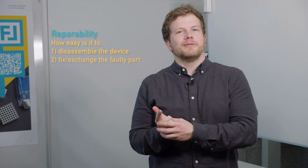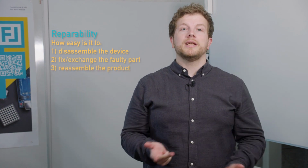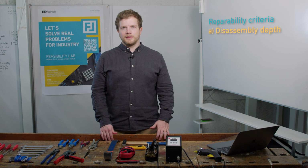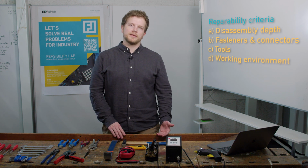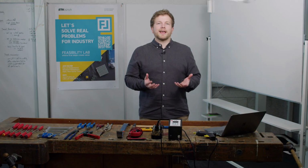Let me quickly recap the learnings from this video. Repair consists of 3 steps. 1. Disassembling the device. 2. Fixing or exchanging the faulty part. And 3. Reassembling the device. The 5 criteria for improving repairability are A. Disassembly depth, B. Fasteners and connectors, C. Tools, D. Working environment, and E. Required skill level.